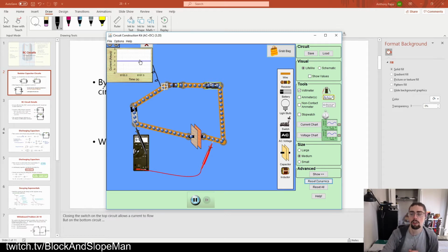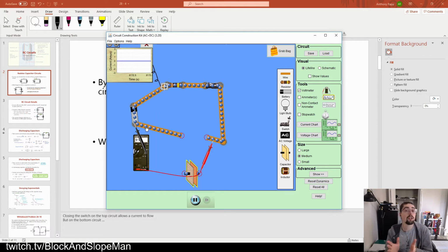For example, if I disconnected this real quick, let me go ahead and split this junction. Let me pull this thing out real quick. We still read that this is at 9 volts. The wire has still technically picked up this voltage. We just assume that the capacitance is 0, but realistically it's a vanishingly small capacitance. But there is a capacitance.